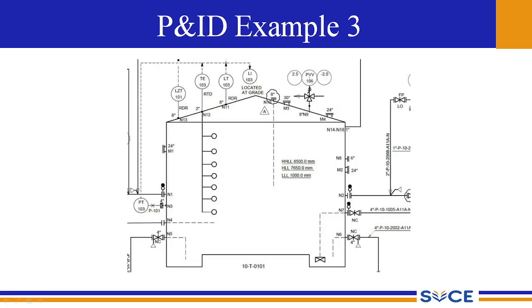The size of the nozzle is also indicated as 6 inches or 24 inches and so on, 8-inch nozzle or 2-inch nozzle, and the size of the various mountings are also indicated by these legends as 24 inches of mounting. So this is about the storage tank, the instrumentation which is present along with this storage tank, with all the necessary information explained to you.